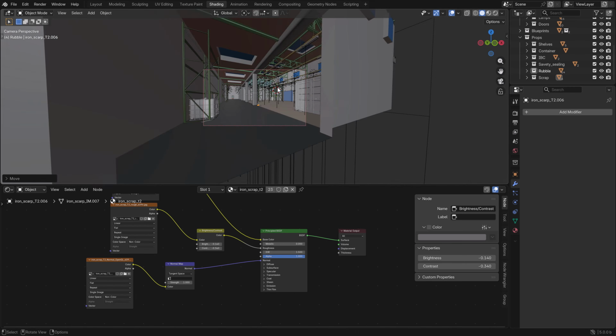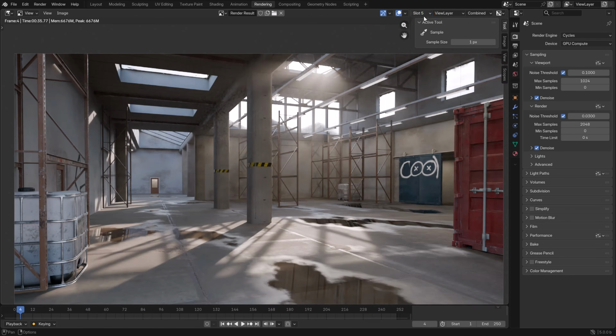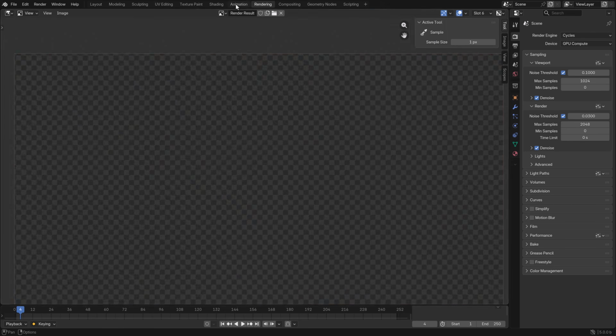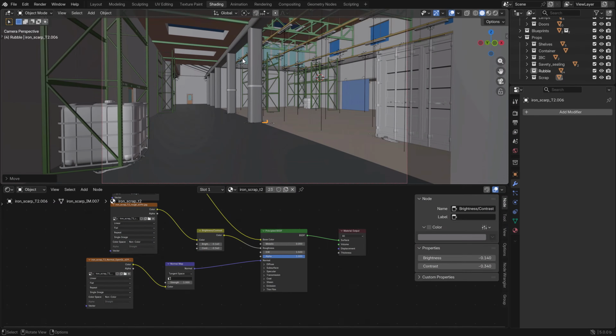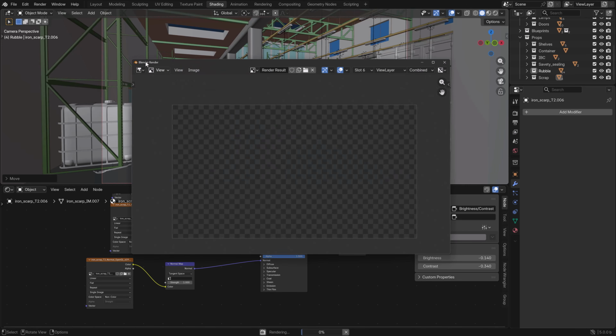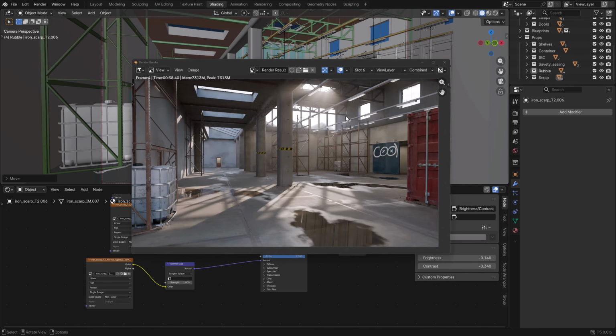What I like to do is just go to rendering, and we go to 6, shading, and we hit render, and look at how this rubble looks. We review it, and then we continue. So here we go for a new render, F12, and we'll pause it. So we have a new render, and I like to just scroll between the first one. Then we improved the pillars, number 5. You can see the damage as well.